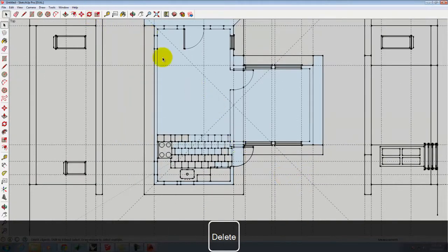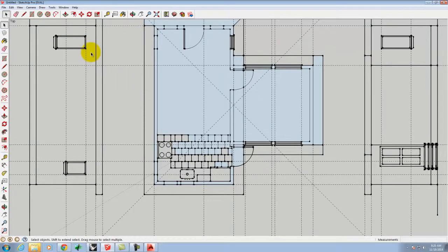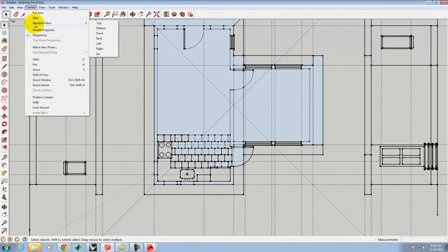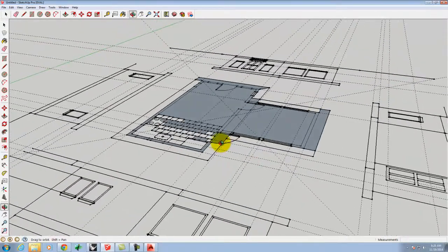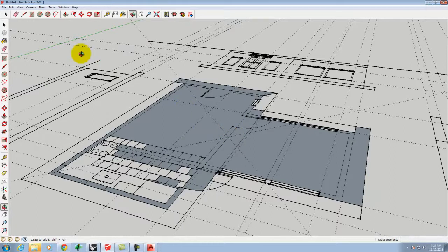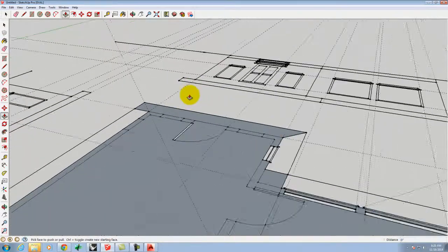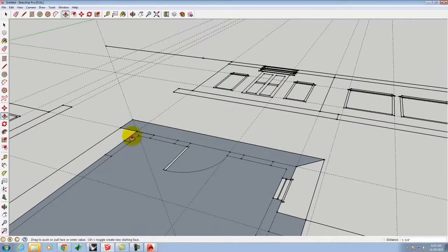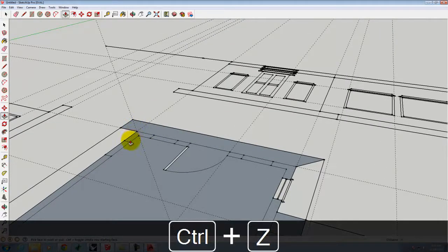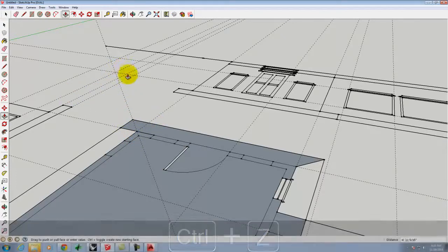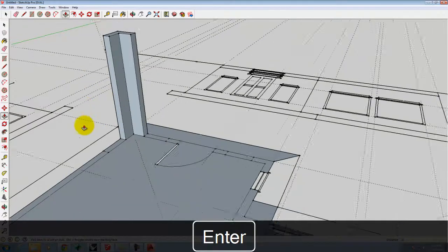Alright, so once I get to the place where I start to have my walls established, for example, let's switch back into the 3D view here. Let me just go to orbit, and we'll orbit like that. Okay. Now what I can do is I can use that push-pull tool that we did before, right, to raise and lower these wall sections. Okay. So let's go on this side here. Let me go ahead and push-pull that section of wall. We're just going to pull it up, hopefully. Come on. For whatever reason, it's going negative on me. Let me just type in a distance. We'll go 8 feet, and that pulls up that section of wall.